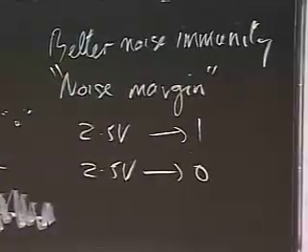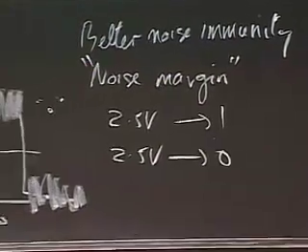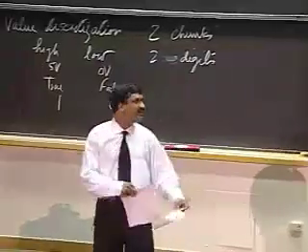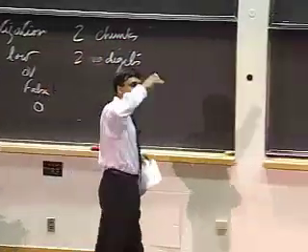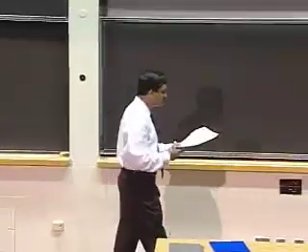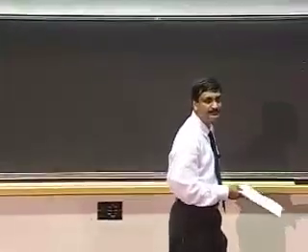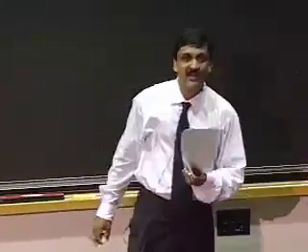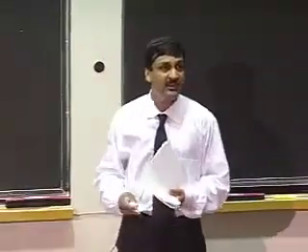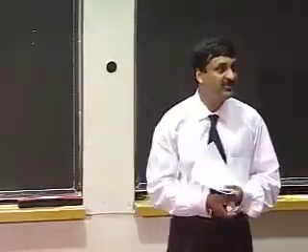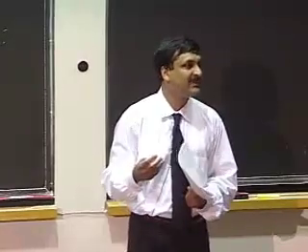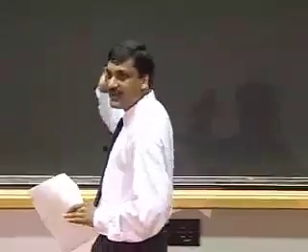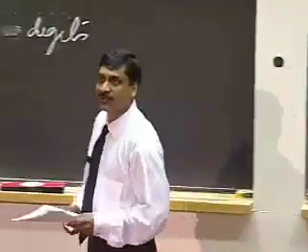So notice that I have a nice little noise margin here, which is simply the English meaning of the term. There is a margin for noise. Even though I can change the signal value by up to 2.5 volts, the receiver will still correctly interpret the signal. So I decided to discretize values into highs and lows, and because of that, if all I want to do in life is send highs and lows, I can send them very effectively. There are many complications, but if all I care about is sending highs and lows, I can send them with a lot of tolerance to noise.